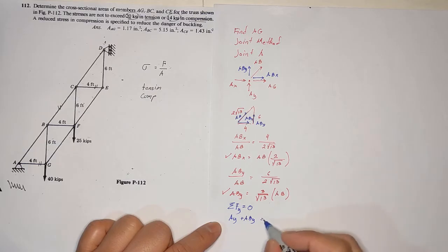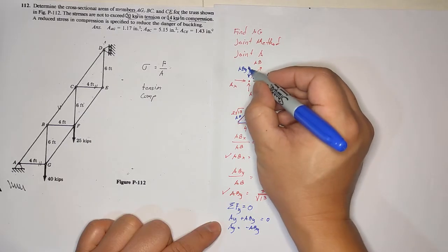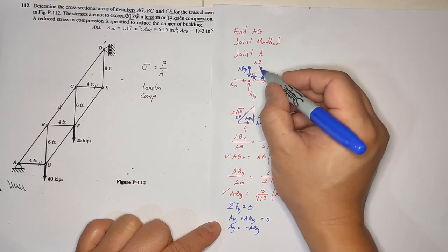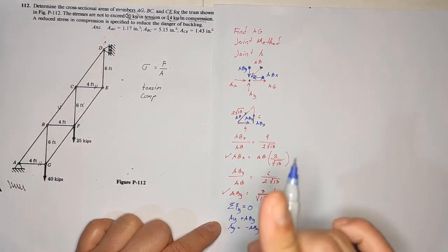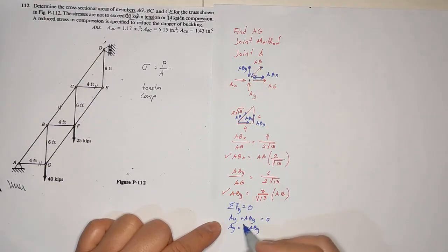Okay. So, you have 0, meaning AY equals negative ABY. Now, if that is negative, your ABY, it means that the direction is wrong. It should be going there, baliktad. It should be reversed. Meaning, if the arrow points to the joint or to the point, it's compression. So, this one should be compression. If that is compression, now ABY would be negative. So, this will be positive.